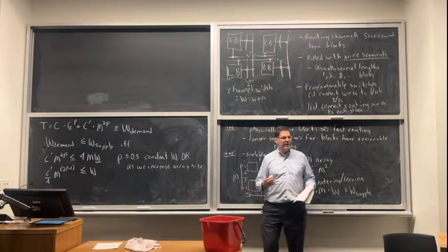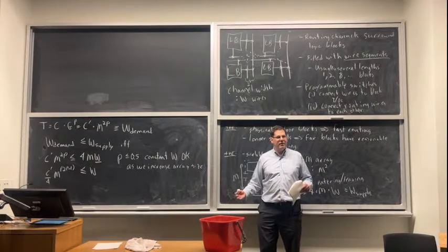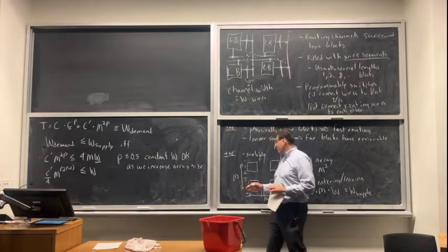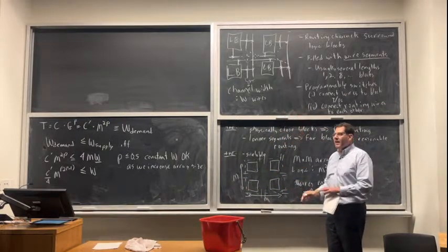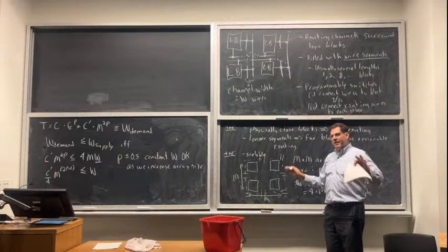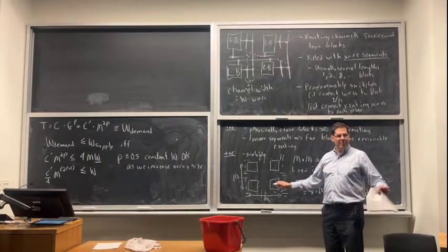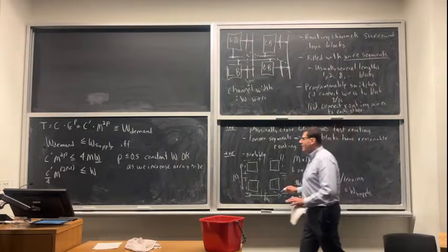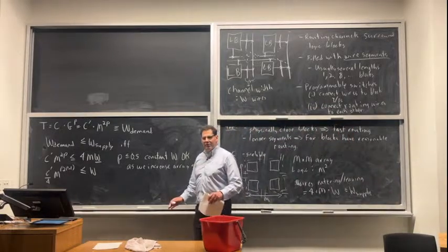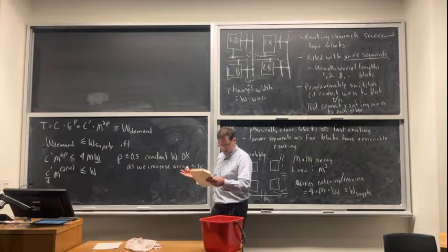For circuits like that, we never get less efficient. We make this basic tile with a certain amount of logic and a certain amount of routing, and we can stamp out a 10 by 10 array, and then a 100 by 100 array, and then a 1,000 by 1,000. They're all going to work fine, right? So that's great. We don't have to re-lay it out. We never lose efficiency.